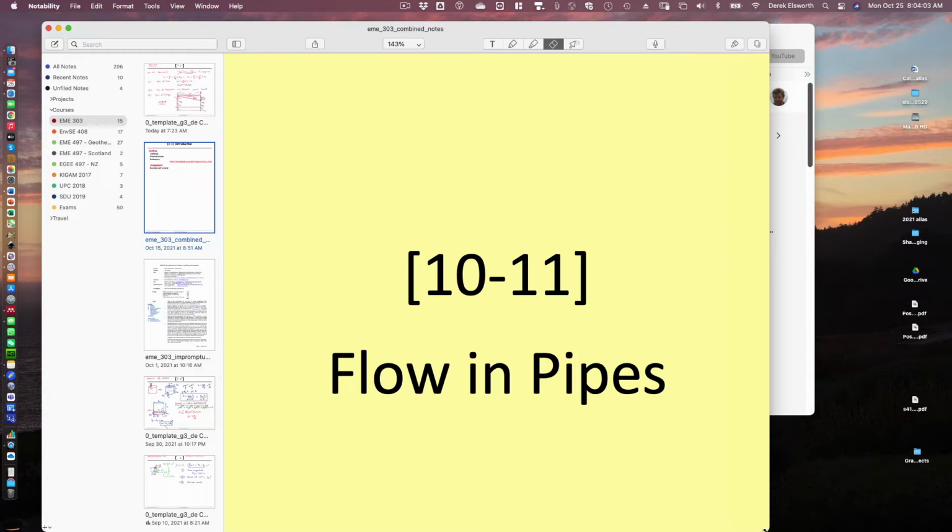So if you want to see if a skyscraper is going to get blown over, you want to know the pressure on the windward side versus the lee side, because that's a force that's applied. If you want to know whether a plane will get off the ground, you'd like to usefully use forces of lift to be able to lift a wing. And so then the two numbers that are important are the Reynolds number, which defines how the flow field looks around the wing, and the second one is the Euler number, which defines how much force you'd have on the wing as a function of the wind speed, or the speed of the airfoil.